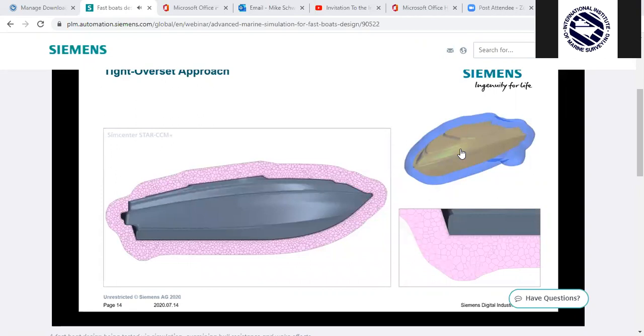We have also added in a few features recently, which help improve simulations by making them faster and more robust. We have recently added in body fit overset grids that are merely offsets of your input geometry. The overset grid, in case you aren't familiar, is the grid which we will use to model the vessel motions, which is then interpolated onto the forced wave type model. So we are doing this to build grids with as few cells as possible, and these are automatically fit to the body of interest, and then they are very free to move easily around the domain.